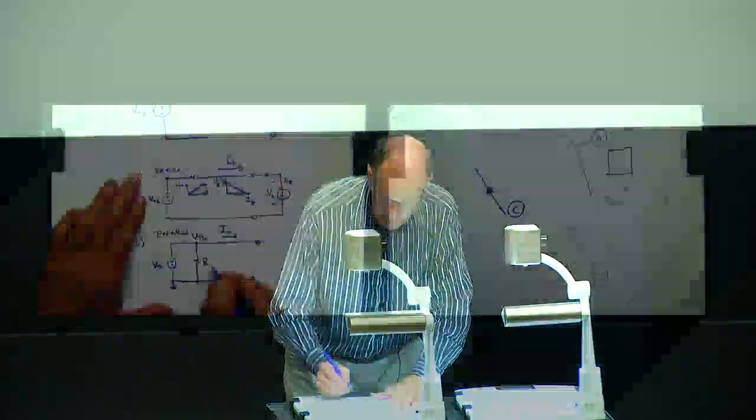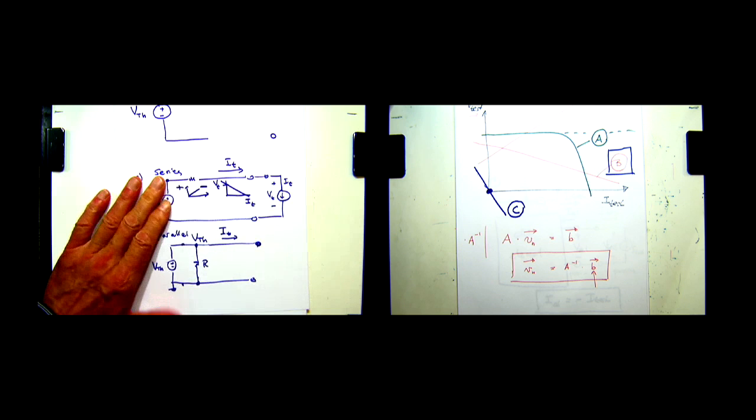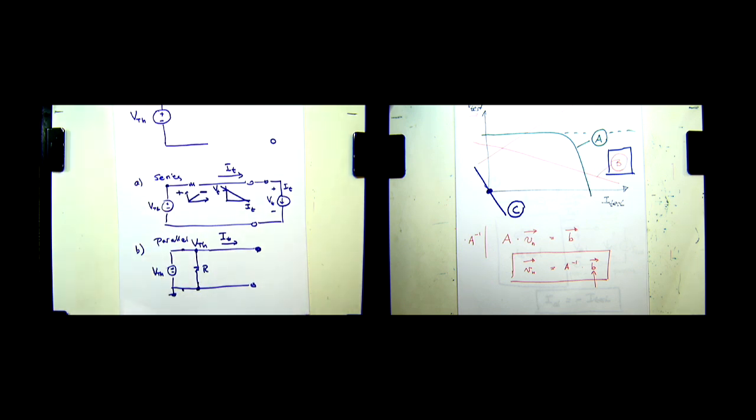So in this circuit, this resistor R contributes basically nothing to the IV characteristics of the circuit. Of course, there is going to be current running through that resistor. How much current flows through this resistor? VTH over R, right? And what happens with the power delivered to that resistor? It becomes heat if it's a normal resistor, or if it's a light bulb, maybe some of it becomes photons. But this thing is kind of just a heater. If you were interested in node voltages and so on, that resistor does nothing.